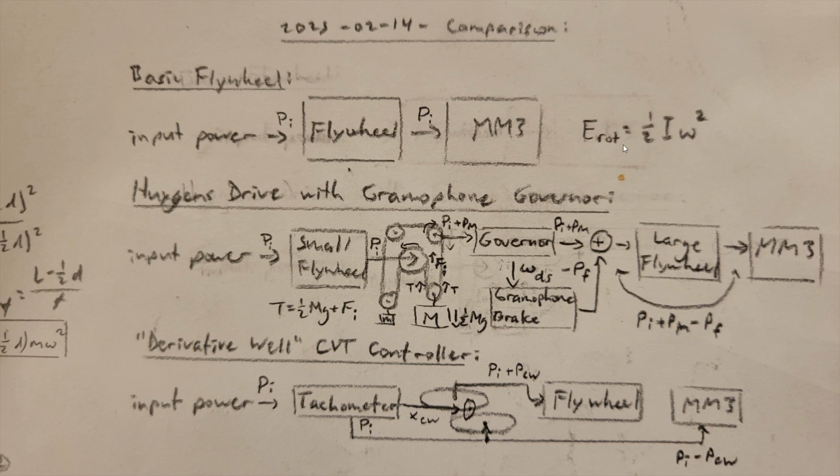But once we add the flywheel, we also maintain a very large moment of inertia, but we use a gear ratio to make it rotate a lot more quickly, and that thus allows us to go from here to this much total energy, and thus for that same change in energy due to the friction or the fluctuations in input power, we will have a lower overall change in the speed.